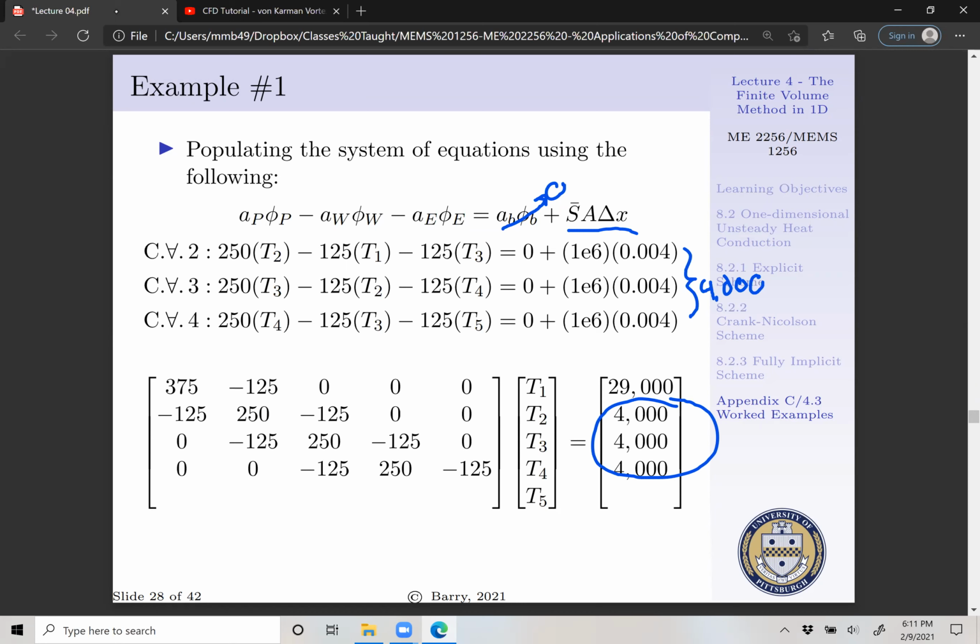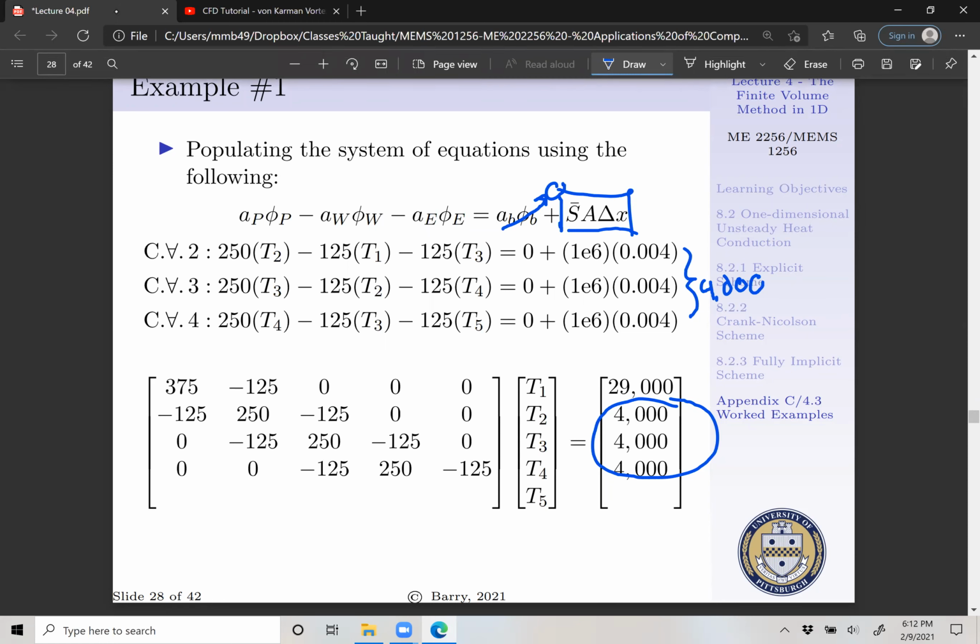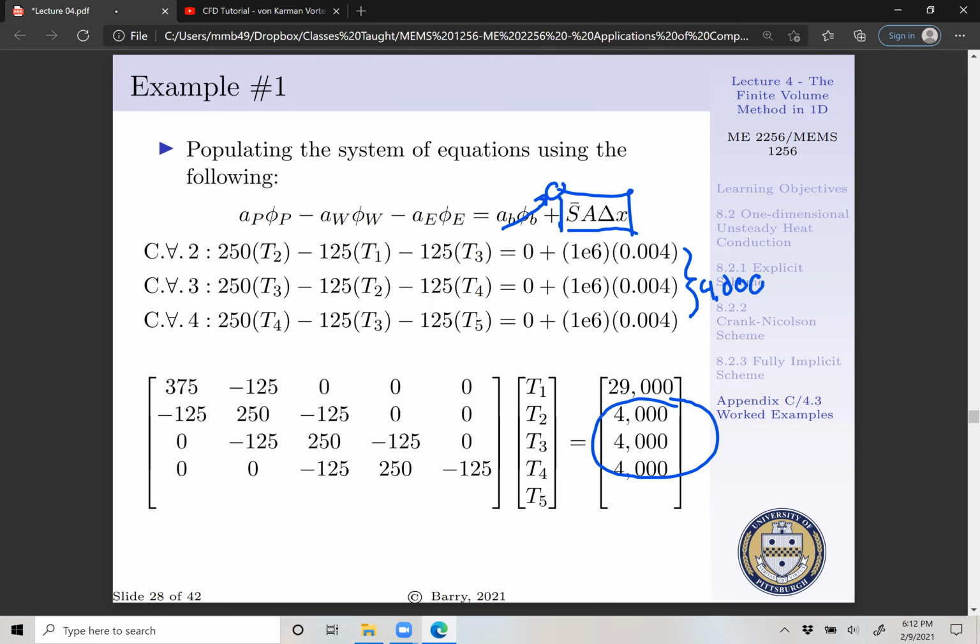The second, third, and fourth entries of our B matrix were typically 0. Now we have a source. We just simply add the constant. I'm sorry, this is really simple, right? CFD seems really, really hard. Numerics applied to any diffusion problem seems really, really hard. We're just adding a constant to this. And here people pay ANSYS $200,000 for a license to solve some heat diffusion problems.